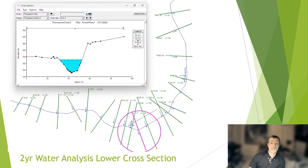This shows the cross section just below the construction site. According to a report done by Golder Associates, the average rainfall for the month of July is 0.8 inches in this area, but the 2-year analysis model was run in order to help predict the flow profile of a possible rain event during the summertime construction window.